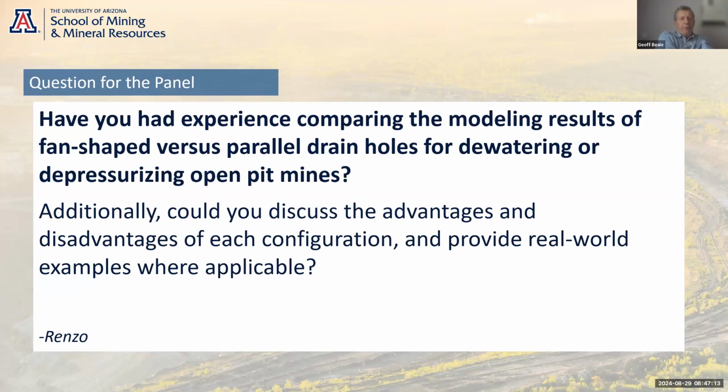In terms of the technical merits, if you're drilling a slope with a bunch of subparallel structures, which is often the target for horizontal drains, then it's often better to drill a series of parallel holes to try and go perpendicular through the structure. So if you're in a situation with parallel structure that's parallel behind the slope, drill lines of drain holes.